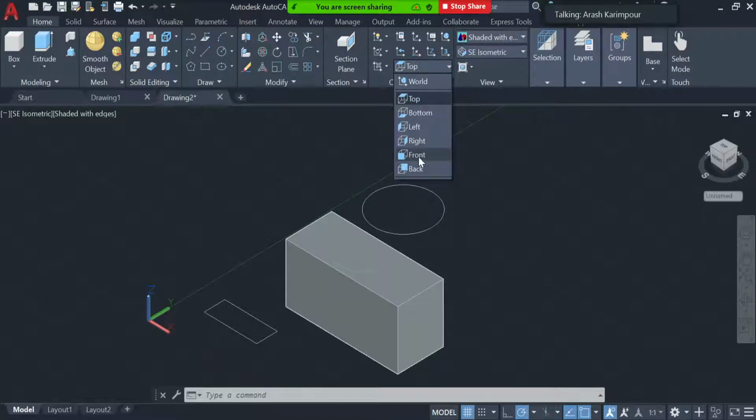And look at here, we have top, bottom, left, right, front, and back. If I click on the back, it doesn't mean that it puts my coordinate system on the back of the object. It means that it rotates the coordinate system in a way that X, Y is still on the front menu, but as if I look at it from the back side. The same here for the right and left. If I click on the left, it's going to put it on the left. If I click on the right, it's not going to put it on the right.